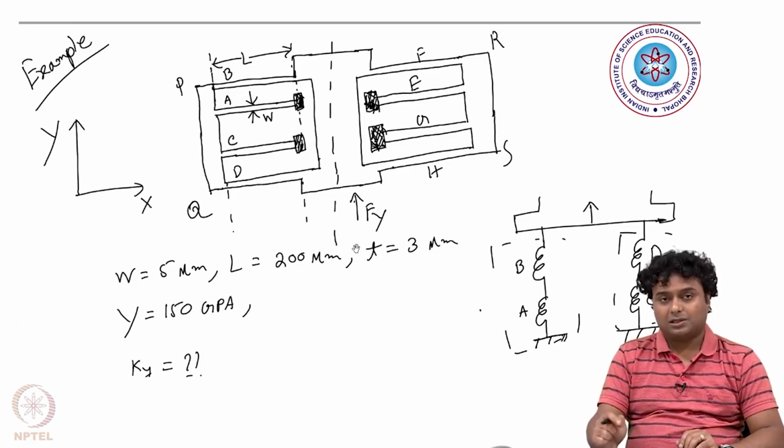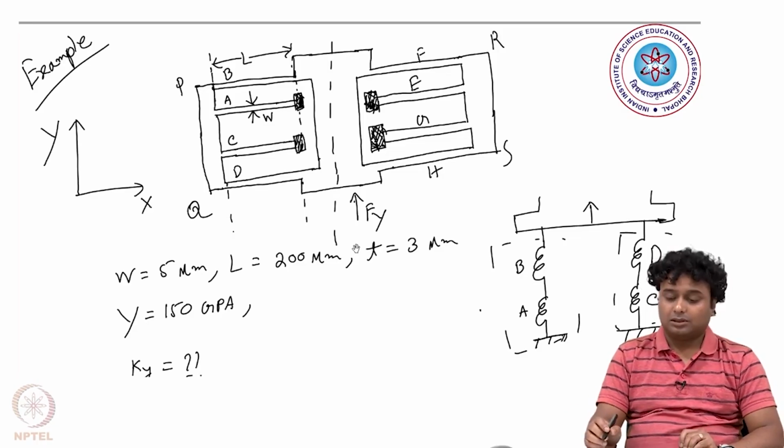For this particular sensor, let's say if it is a force sensor, then we can measure the deflection. If we measure, let's say, the deflection of this proof mass to be about 0.5 micron or 500 nanometer in the y direction, then we know that the force applied is 7 micronewton, right? So this is how we can calculate, and with that we will close this module. Thank you.